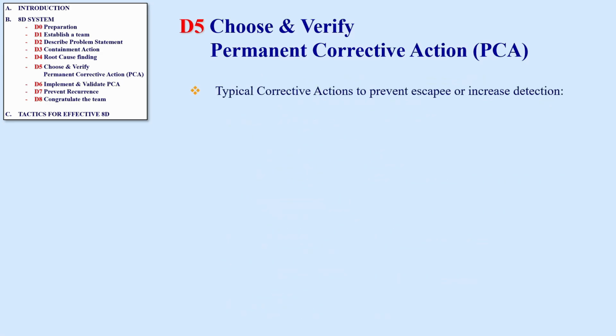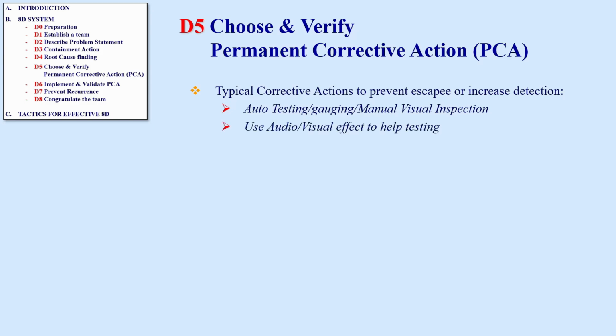Let's move from corrective actions to prevent reoccurrence to corrective actions to prevent escape or increase detection. The typical corrective actions to increase detection include automating the testing, use of go-no-go gauge, enhancing manual visual inspection, use of audio or visual effect to help testing. For example, trigger a buzzing sound, or turn the monitor screen red, to attract the attention of the operator when there is a reject.